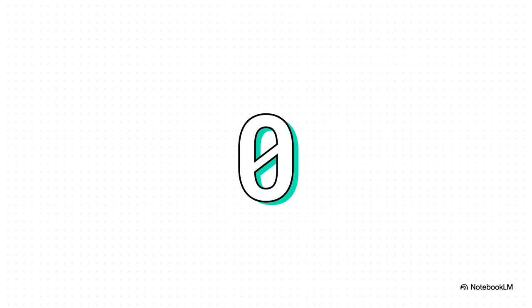So, how many gates does our new super simplified circuit need? The answer is 0. That entire 3-gate mess simplifies down to just a single wire connecting input A straight to the output Y. That is the magic of Boolean algebra. We just went from 3 components to none, saving space, cost, and power on a microchip.